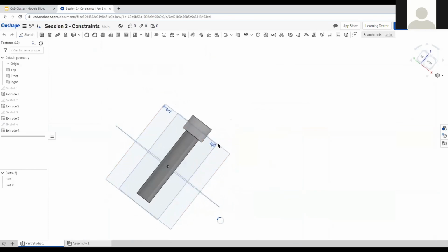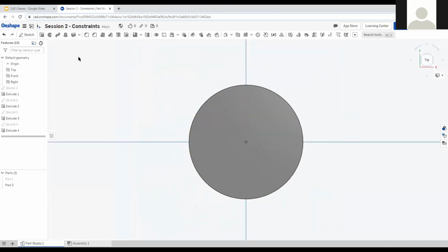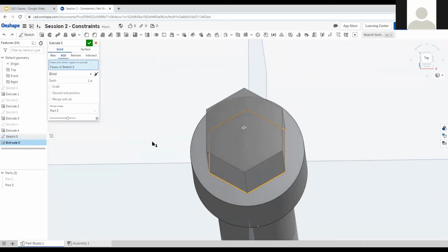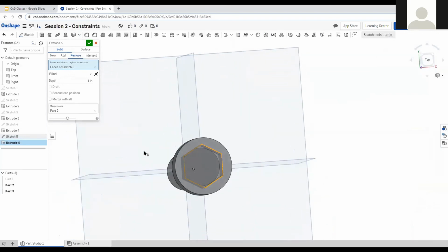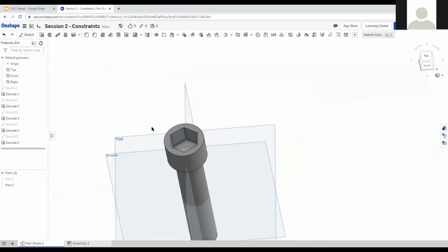Yeah, so I have my bolt, and this looks pretty nice, but okay, how am I going to turn this? There's no good way to turn it. Well, the only real way to do that is with hex. I don't care what anyone else says, hex is clearly the superior form of bolt. We're just going to create a little hex head. How large do we want this to be? Let's go with 1 inch. It's massive. Since we want to be able to actually turn that, let's not just have it extrude out, let's have it remove. And we don't want it to go all the way in, so let's go 3/4 of an inch. That sounds pretty good. So that's our bolt now.